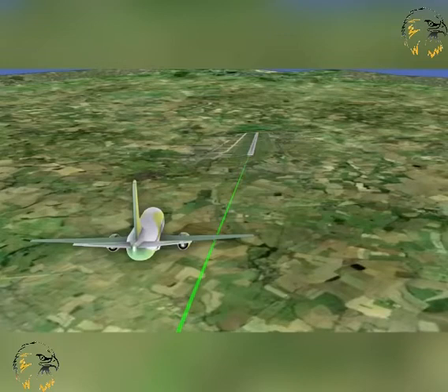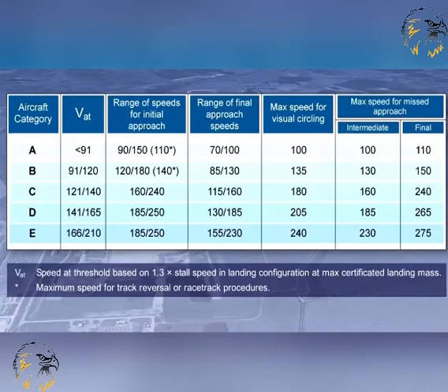track. All procedures depict tracks, and all pilots must attempt to maintain the required track by flying accurately and applying corrections for known wind. Whilst flying an ILS precision approach, pilots are expected to be able to fly the aeroplane during the final approach phase with a track accuracy equal to no worse than half full-scale deflection of the ILS indicator needle. Aeroplane performance has a direct effect on the airspace and visibility needed to perform the various manoeuvres associated with the conduct of instrument approach procedures.